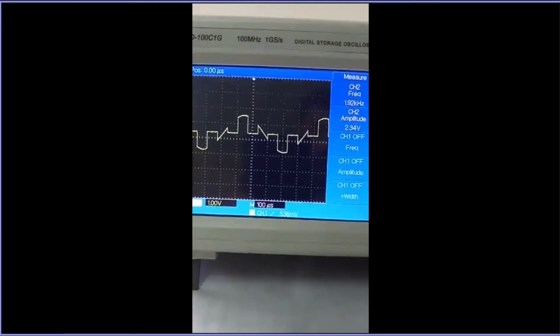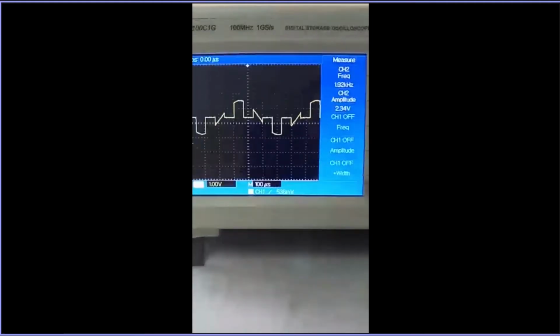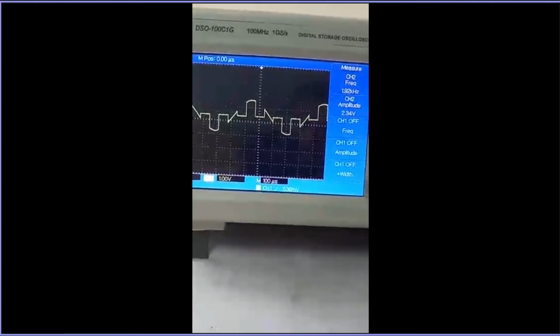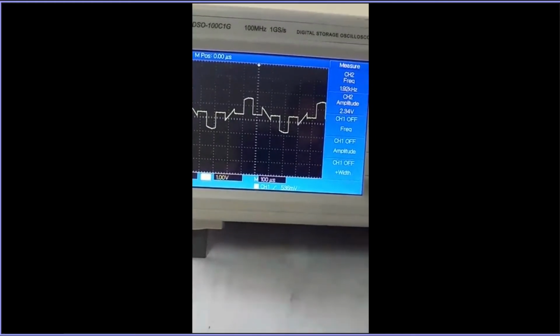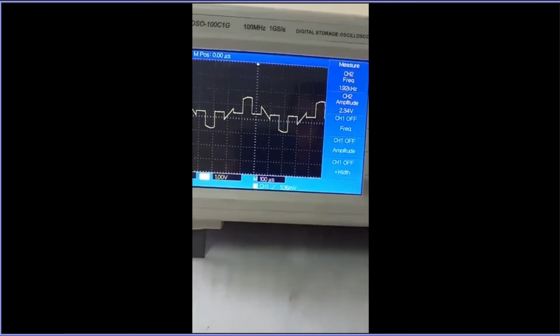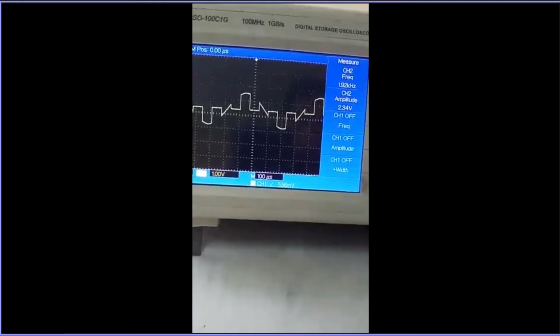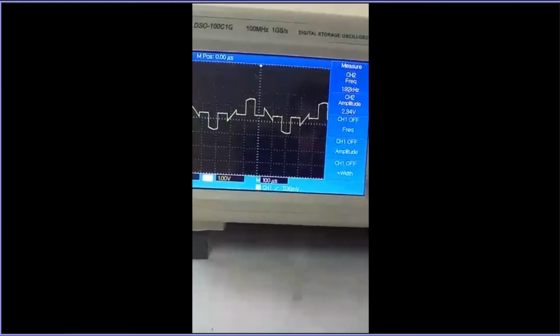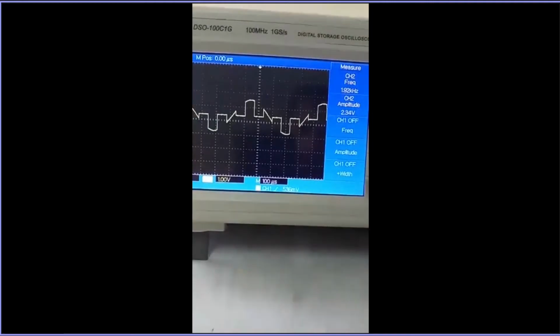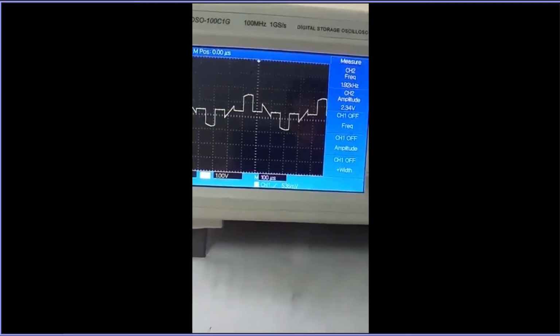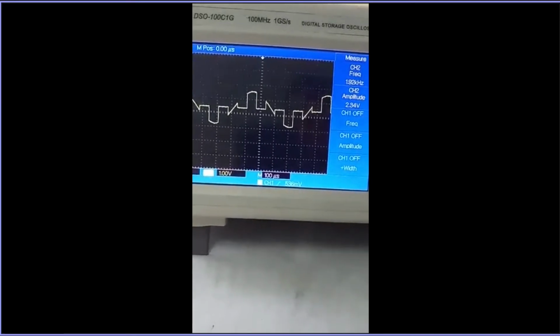Here the tops are not flat, you can see. Right, tops are not flat. This is natural sampling. Here we have just multiplied the signal with the train of impulses. That's all. No signal conditioning is done. Please have a snapshot of this. And now I will try to reconstruct the signal back. For that, we'll apply the same low pass filter, second order, which is an integrator only.